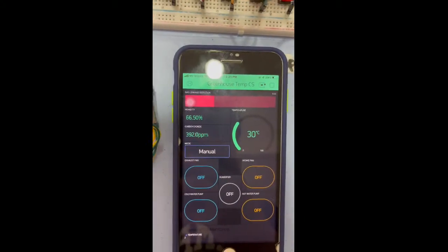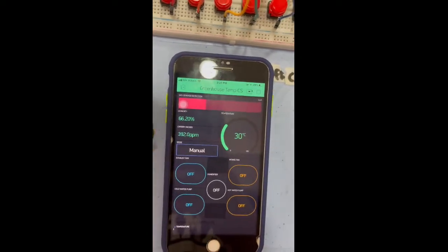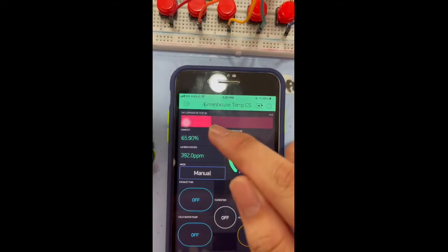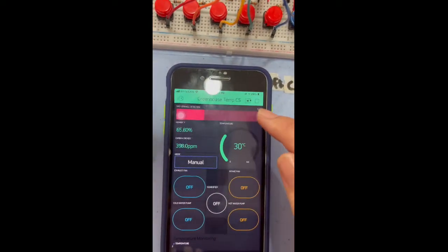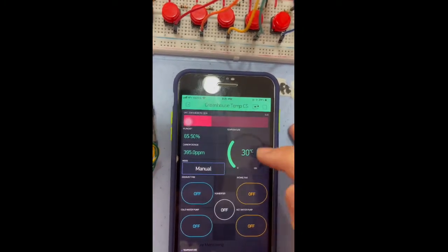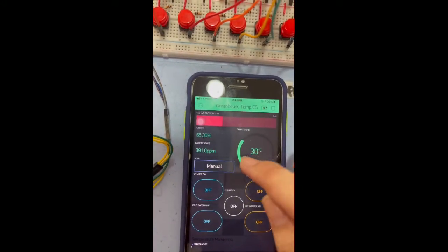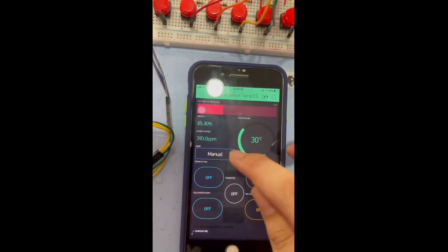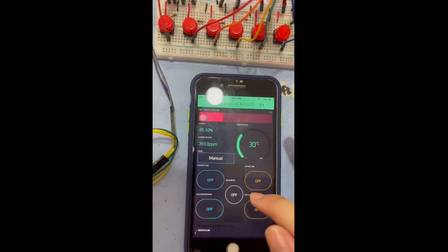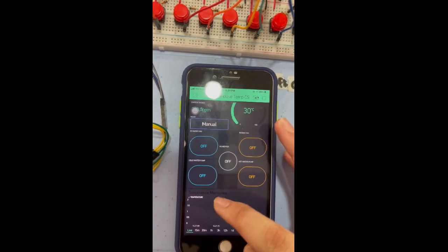This is the UI interface for this greenhouse temperature control system in Blynk. Here we have the gas leakage detection in the first one. This indicates the status. Whenever gas is detected, the red bar will increase until here. And here are the humidity, carbon dioxide and temperature values. This mode shows the current mode now. We have manual and automatic mode. And we have the pins to control the relays here. Also a chart here to show the temperature monitoring chart.